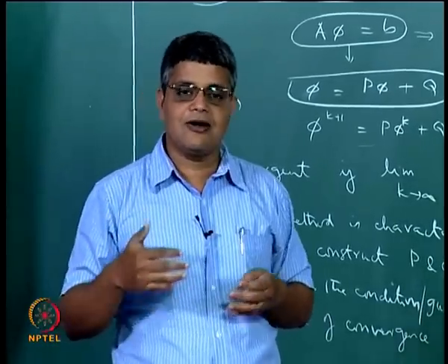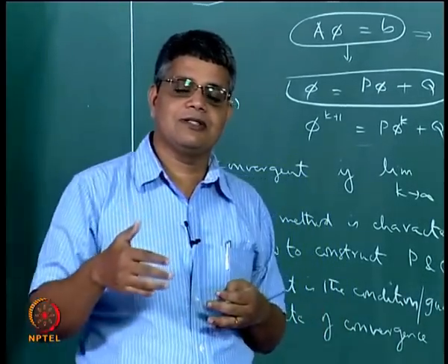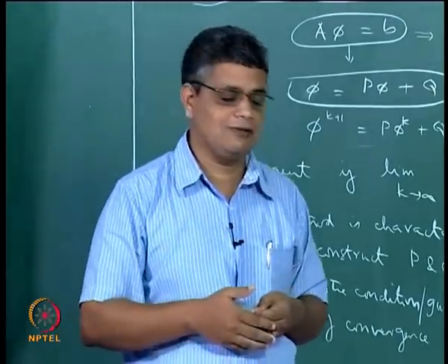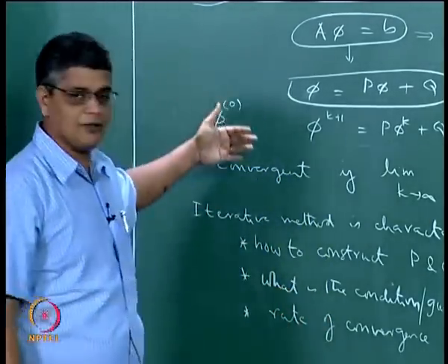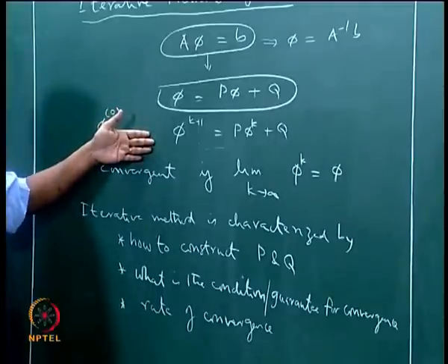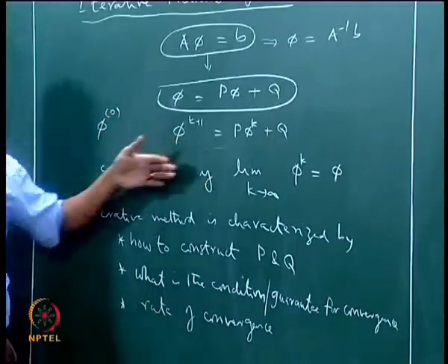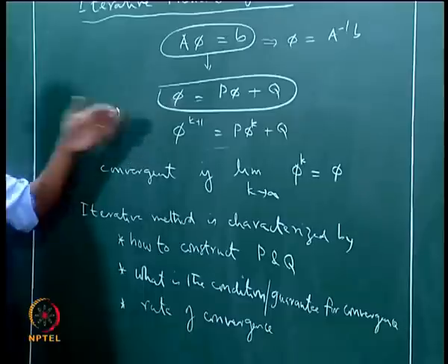So in the context of sequential solution of the x y momentum equations and the continuity equation, an iterative method which provides us an ever improving solution as we increase the number of iterations is a good choice.